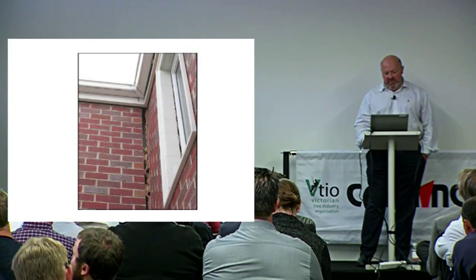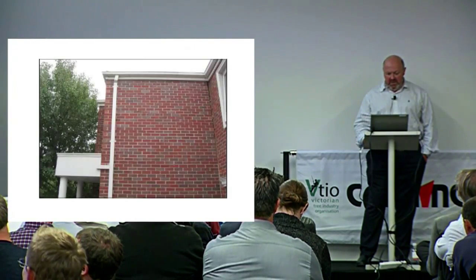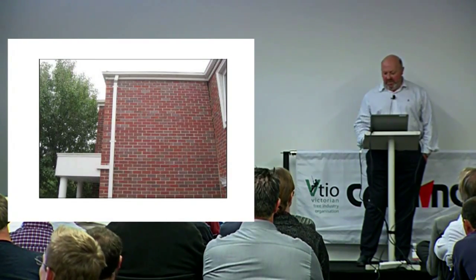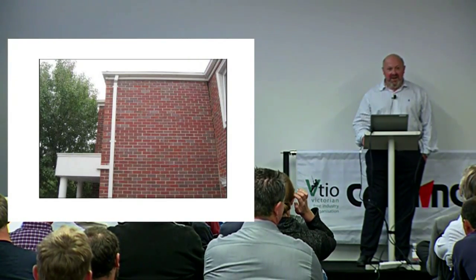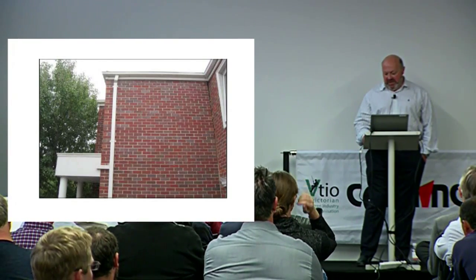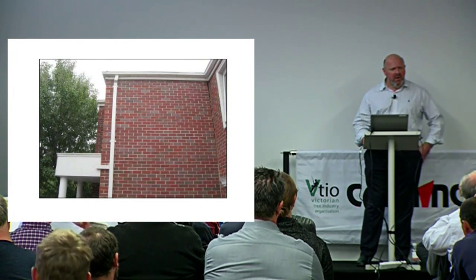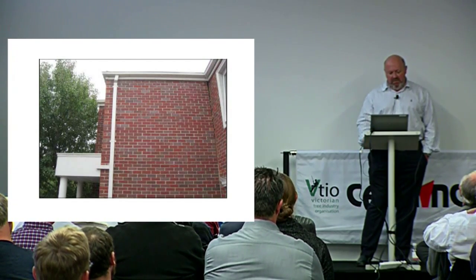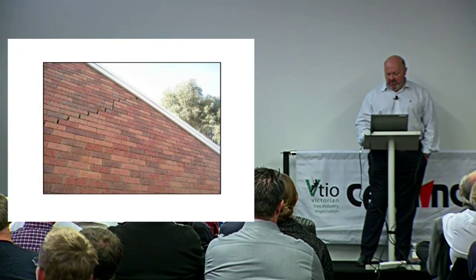This again is wall rotation away on a moderately reactive clay site in Ringwood. Quite significant rotation, and that's the reason. Manchurian pears, like, I'm not a tree expert, but man, they've been causing us a lot of problems. Well, I didn't know whether it was because the fashionability of them had increased or because people plant them in groups, but a forensic arborist came down from Sydney. It's the rootstock they use. Yeah, she said they're grafted onto really aggressive rootstock, which makes sense because they seem to be drying much more than you'd expect. Again, typical crack pattern because of soil drying.